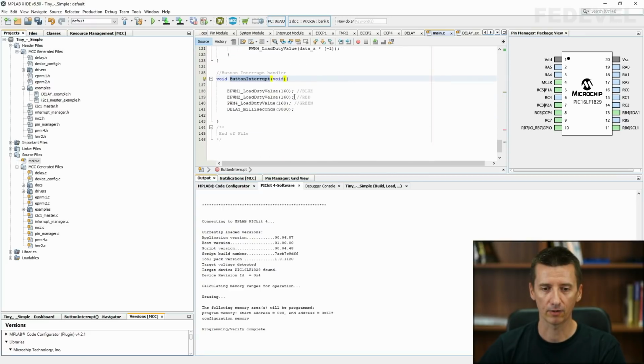And inside of this function is what should happen when we press the button. At this moment, it's something super simple. You can see basically when we press the button, our LED should get white for 3 seconds. This is maybe not the best example of what you should use in interrupt functions because it takes a long time to execute, but this is just an example, okay?